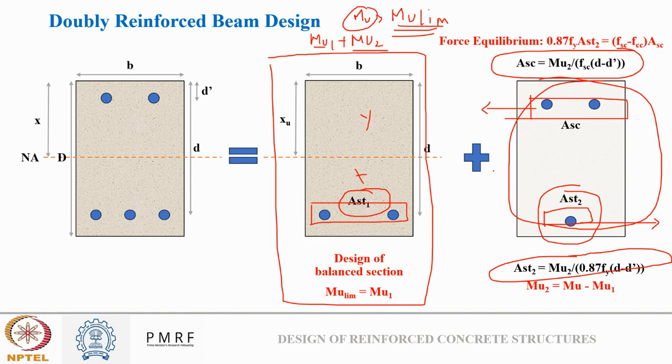Since the concrete has been used to balance steel in part 1, we have steel here in both directions so that we can maintain equilibrium. Will both of these areas be equal? No, because we saw just now that the strain value at both levels can be different.